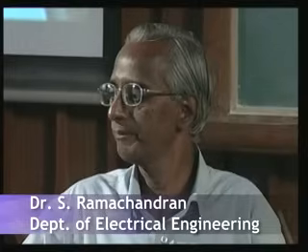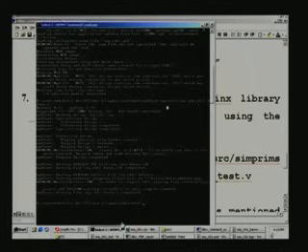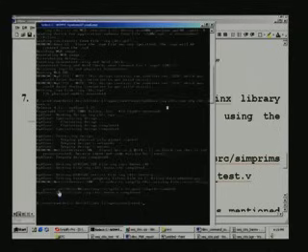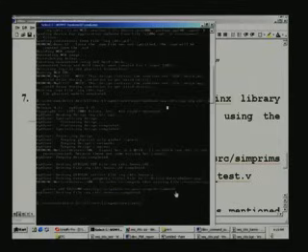Have any question? Why did you do that commenting out? That is because it has asked for some comments here. I will find out what that comment is. What it says is, please add Xilinx's Verilog source glbl.v to your compile command, because these are all reserved words.